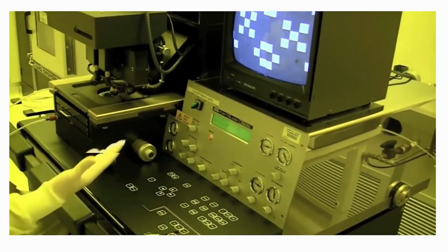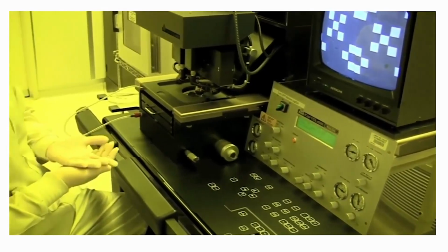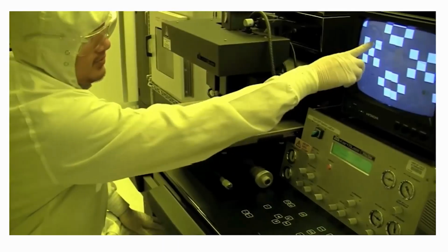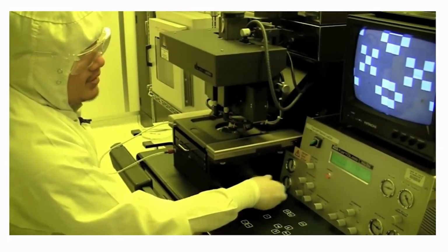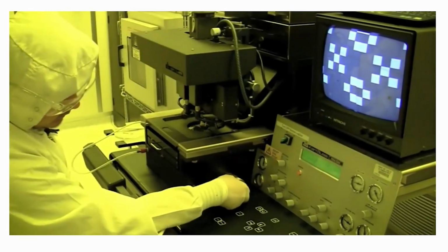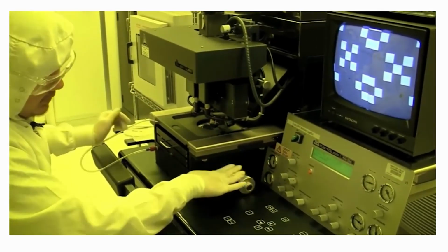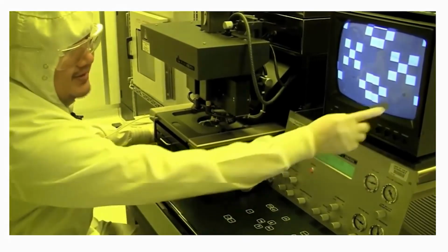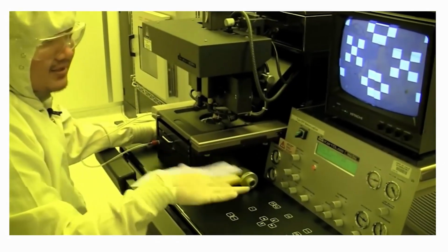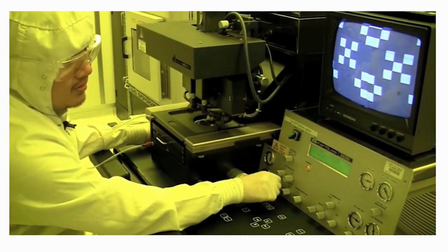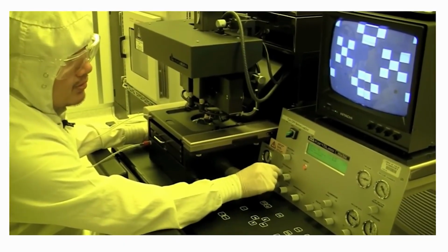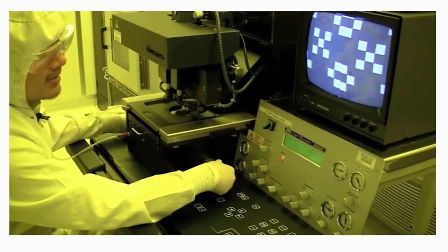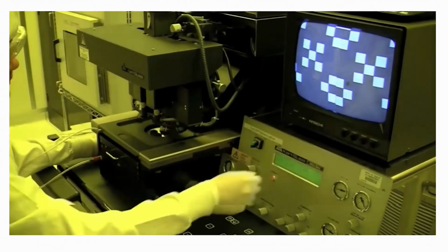So what you would do is similar to backside alignment. You would align your alignment marks on your wafer to these right here. So you can see that if I move this, these knobs always control the substrate. So when I move this, you can see that this has been moved. So you can tell that's the actual substrate moving, not the mask. So you try to focus it, and you try to find your alignment marks and align them to the features.